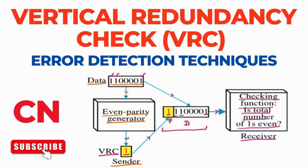Let us say we are using even parity with the data bits 1110010. The number of ones is 4, so the parity bit will be 0. The transmitted data will be this one.